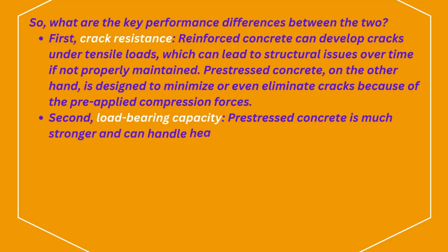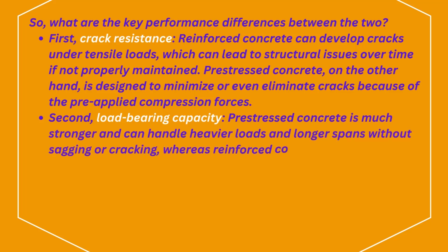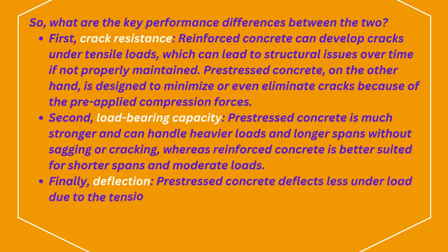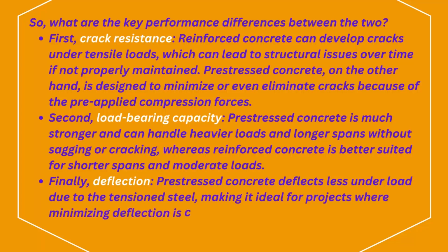Pre-stressed concrete is much stronger and can handle heavier loads and longer spans without sagging or cracking, whereas reinforced concrete is better suited for shorter spans and moderate loads. Finally, deflection. Pre-stressed concrete deflects less under load due to the tension steel, making it ideal for projects where minimizing deflection is critical. Now, let's talk about cost and complexity.